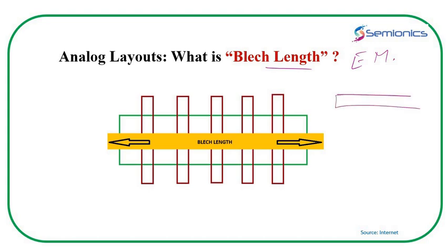Say there is a piece of metal. In due course of time, because of continuous flow of current, the metal tends to break, tends to fuse. There is a displacement of metal atoms which will cause the metal to break and fuse, because the electrons tend to migrate from that particular location. Hence the term electromigration.